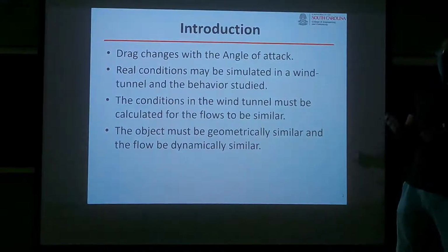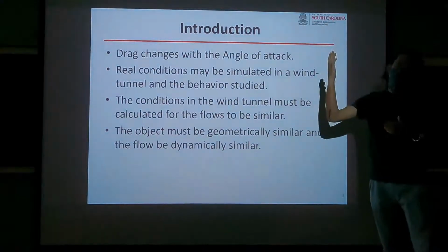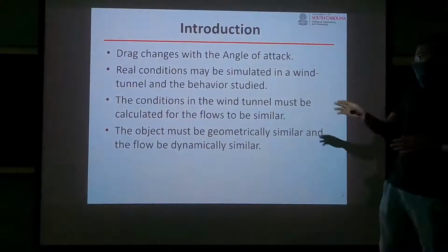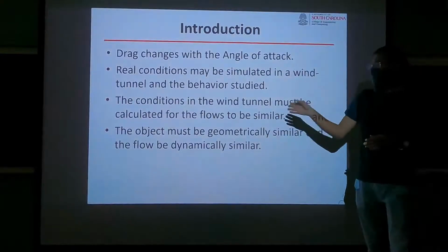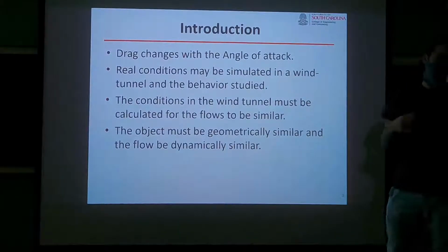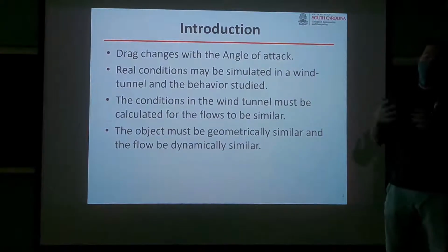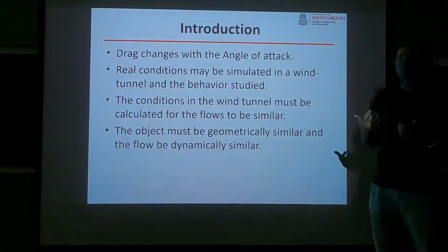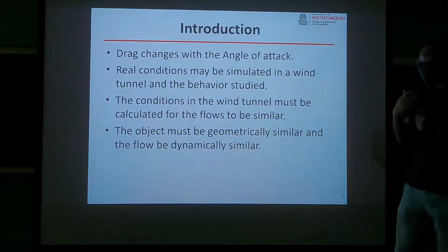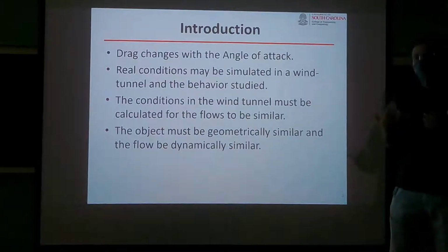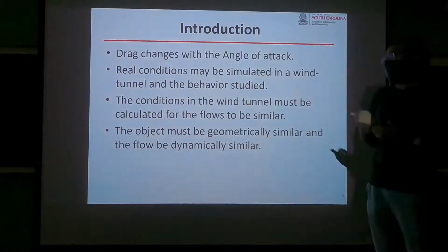So we know that real conditions that the airplane experiences, we can simulate in the wind tunnel. The conditions in the wind tunnel must be calculated for the flows to be similar. The flow has to be similar geometrically, and the object should be geometrically similar, and the flow should be dynamically similar. Once this similarity is achieved, you should be able to get good results in the wind tunnel.